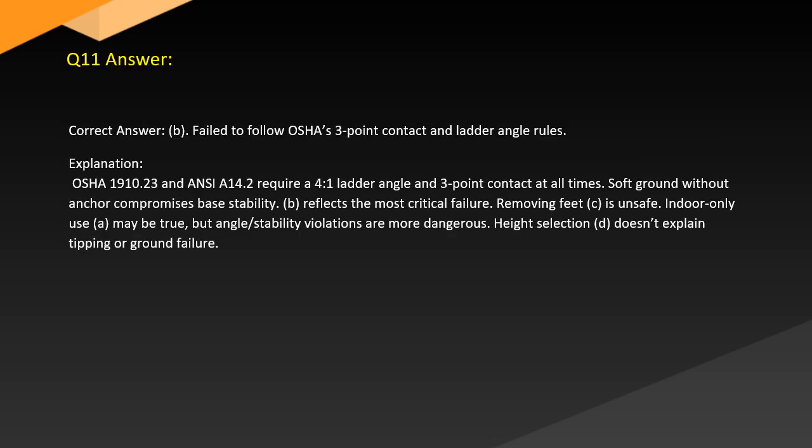Answer. Correct answer: B. Failed to follow OSHA's 3-point contact and ladder angle rules. Explanation. OSHA 1910.23 and ANSI A14.2 require proper ladder angle and 3-point contact at all times. Soft ground without an anchor compromises base stability.